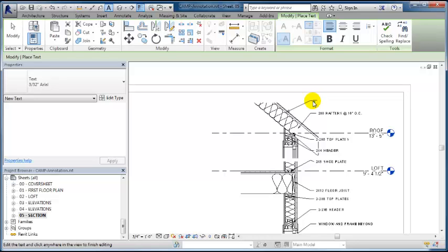Probably going to be at least, I would think it would be at least 3/4 sheathing. Otherwise, it kind of gapes in between the rafters. And then we have underlayment and asphalt shingles.